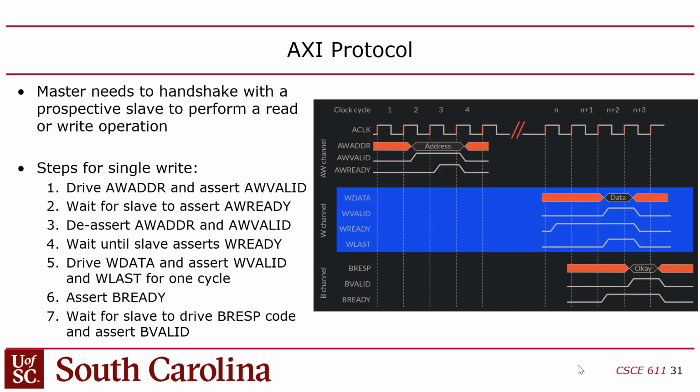Now the address does two things. The address addresses a peripheral, right? But it also has a sub-address within the address space of that peripheral, like a register address, right? So you have to say, well, I want to write to the JTAG or the UART, because I want to print hello world. So I have to write to the UART interface, and I have to target a specific register within the interface to tell it what I want to do in there, right?